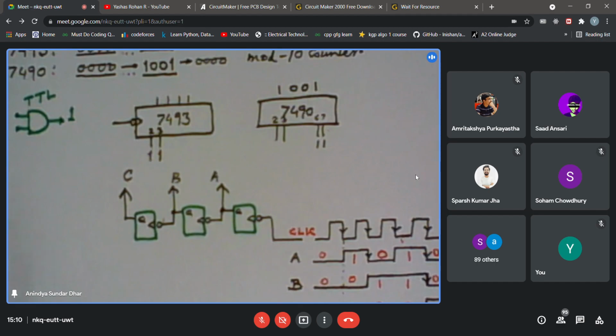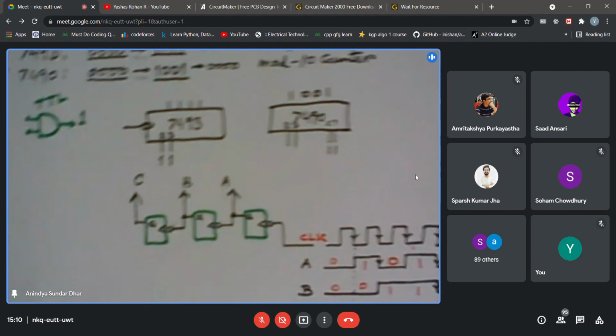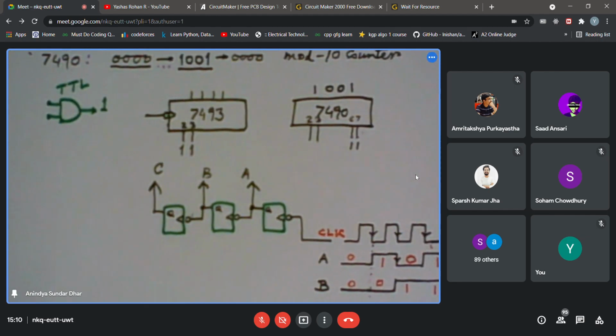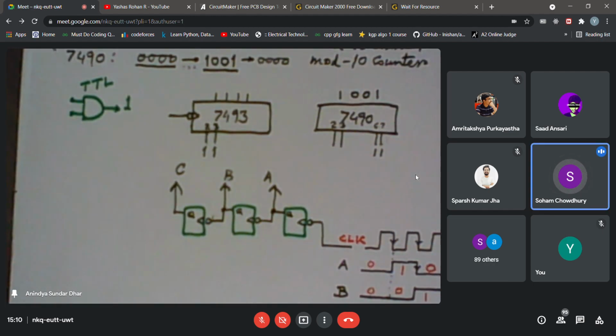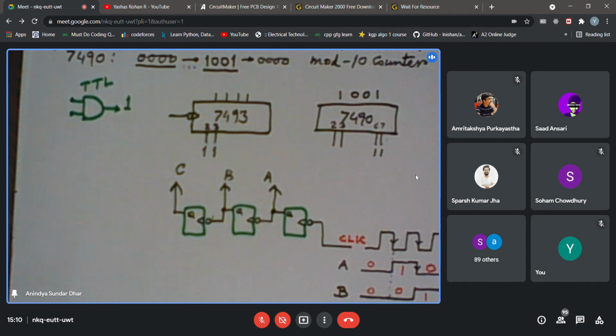Now, if I ask you what I should have got inside a 4-bit counter, what should be the difference between the drawing I have made and a real 4-bit counter? So what would be your answer? I think with the last MSB output, if you take it as a clock and once that goes for falling edge, then only the leftmost will toggle. Actually, you are answering the question which I have not asked yet. I was about to ask my second question. So you have answered a question which your friends are perhaps not yet aware of.